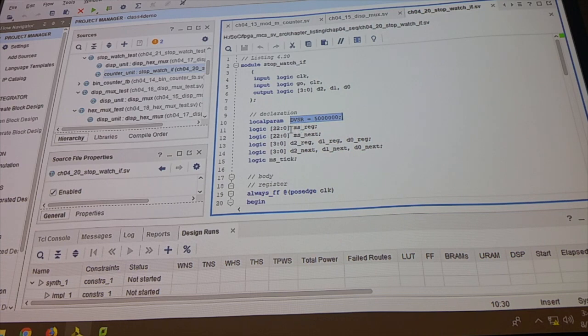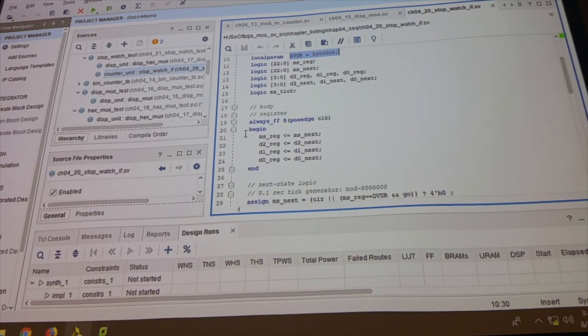And then, again, it's just the 2 regs, right? He needs 23 bits to be able to count that high. If you have to go to 100,000, you have to add another bit. And then he only needs 4 bits to count a decimal number and the appropriate decimals. So when he gets to the flip-flop area, this is the counter to count milliseconds, and then you've got your 3 decimal digits.